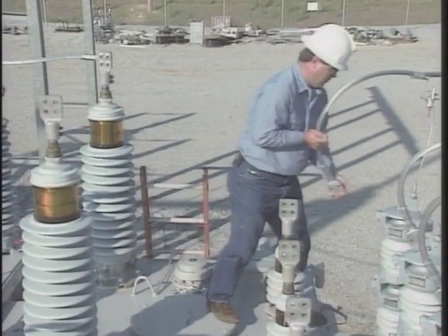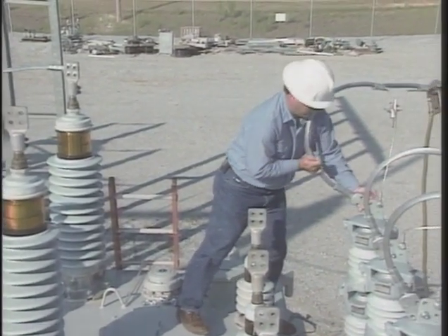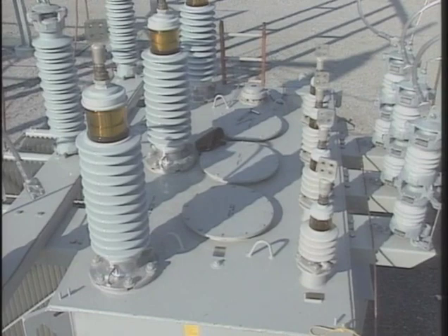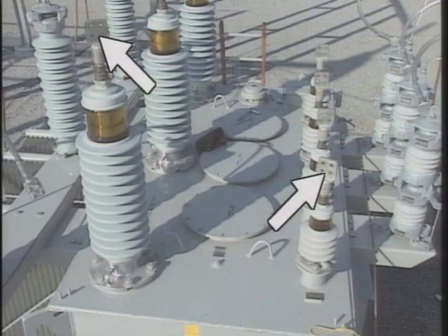This is typically done by lifting the conductors from the transformer terminals with the ground still attached to the conductors. However, if there's energized high-voltage equipment nearby that may induce voltage in the transformer windings, it may be necessary to keep a ground on one end of the high-voltage winding and on one end of the low-voltage winding that are being tested. All other grounds would be removed.